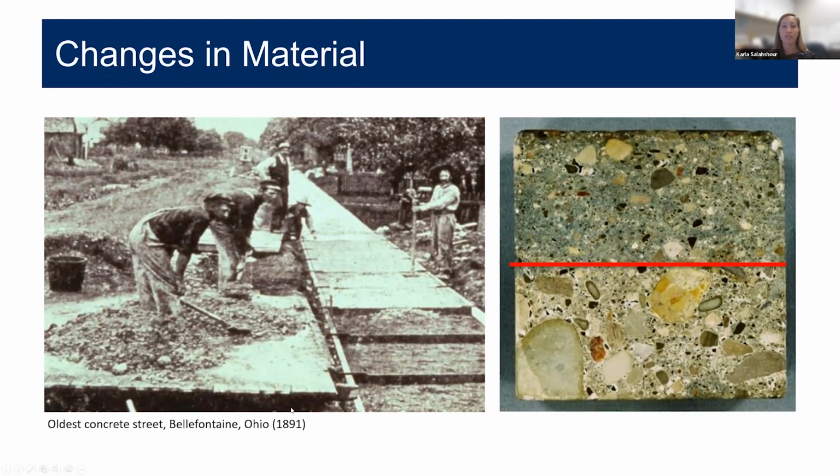The other thing to note is that historically, cements tended to be much coarser ground due to the high cost associated with grinding cement clinker. But then we saw developments in the mills and mill technology and grinding and the use of higher grade iron ores. And so it allowed for the finer grinding of cements today than has traditionally been done. And so that brought a lot of changes to the properties of the concrete. And that again is an observation that can be made petrographically.